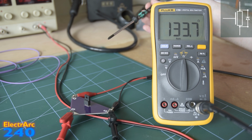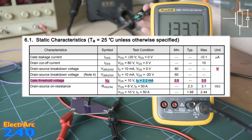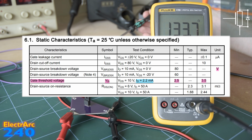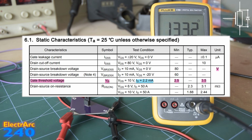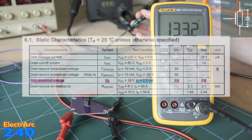Don't worry, you're not alone, and if we take a closer look at the datasheet, we can see the threshold voltage is actually specified for a particular drain current. So basically they're just saying, at this gate source voltage, this current will be able to flow. Now there is some physics stuff to do with electron density that determines this current, but really we don't care about that. We just care that the threshold voltage is still a good way to compare MOSFETs, even if it doesn't mean what we'd like it to mean.